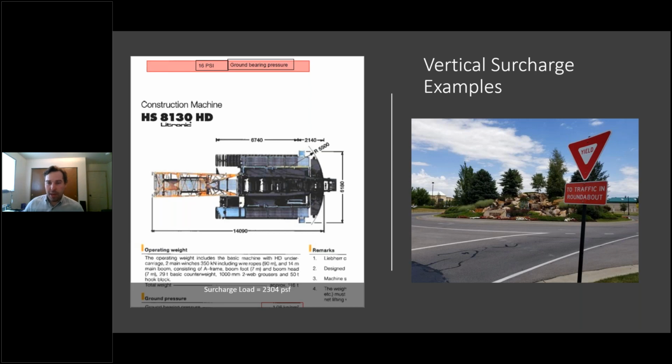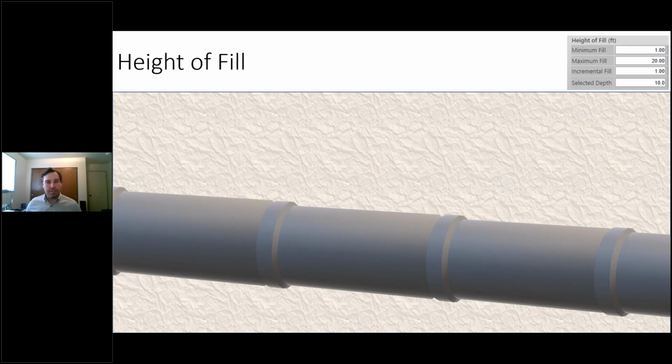Luckily, they ran some cameras through it, didn't find any longitudinal cracking. Turned out the pipe was fine, and that's one of the benefits of using concrete pipe, the increased loading capabilities. But we do also recommend, if you're going to load an extra 15 feet of fill over an existing pipe, have one of the manufacturers run some designs, run your own designs, and make sure to video the pipe afterwards.